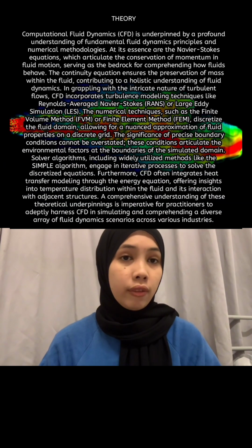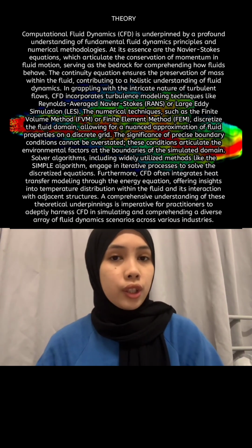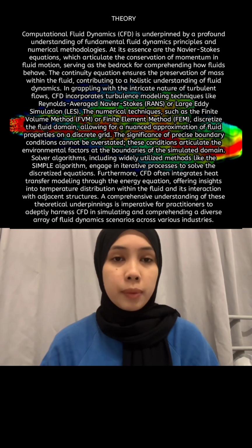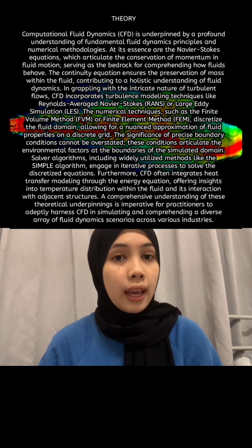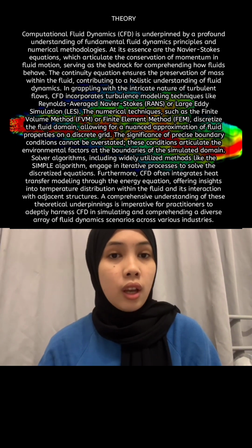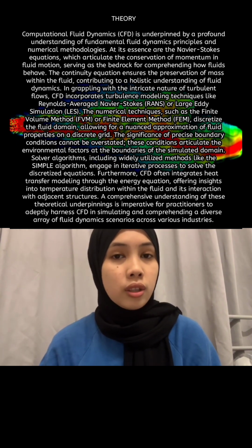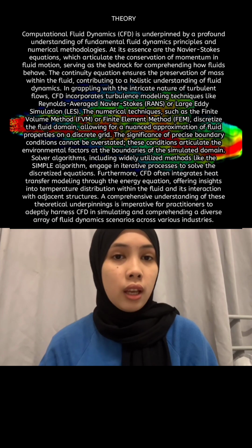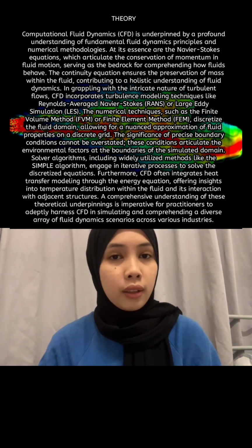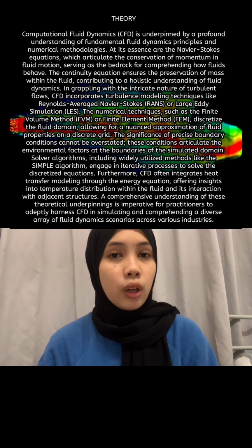So the theory related to this topic is computational fluid dynamics. CFD is underpinned by a profound understanding of fundamental fluid dynamics principles and numerical methodologies. At its essence are the Navier-Stokes equations, which articulate the conservation of momentum in fluid motion, serving as the bedrock for comprehending how fluids behave. The continuity equation ensures the preservation of mass within the fluid, contributing to a holistic understanding of fluid dynamics.